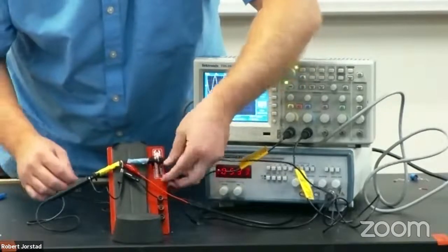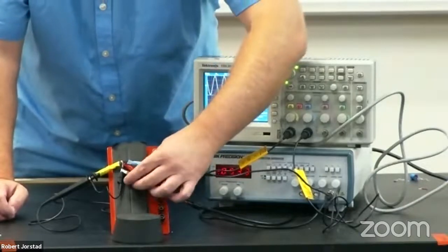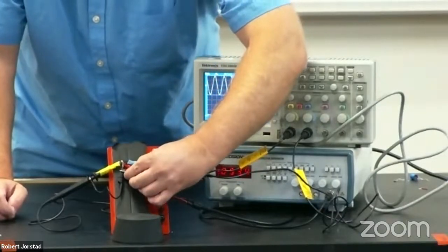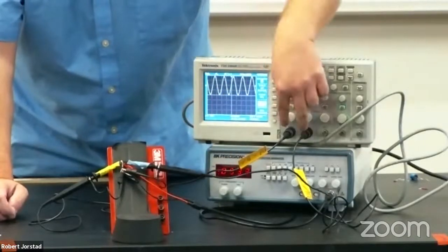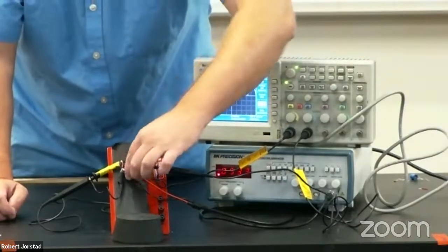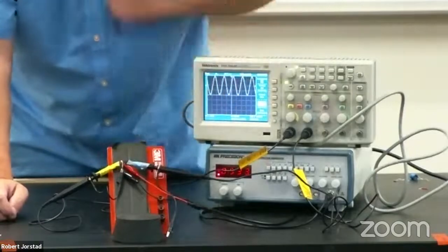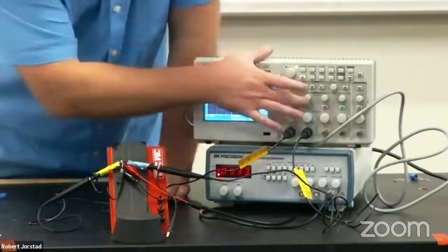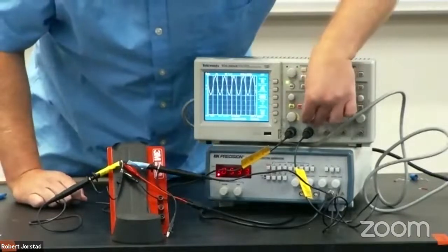So interestingly enough, normally when you connect a DMM, you have to clip both leads on here like this, right? But since this is a DMM with more than one voltage reading tool, this is common to both measurements. I only have to clip it once. This is the ground for both of these because ground is common. All right, so now in this case, I'm going to turn on this, and shocking, there's nothing exciting going on.